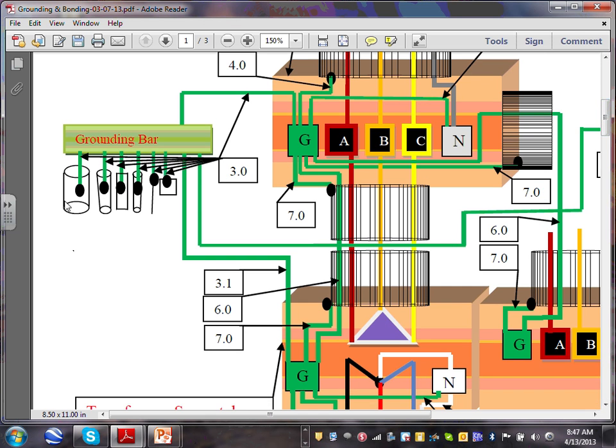Okay, so mind my graphic here, but this is supposed to show that you can use multiple of them, guys. As you know, you can have a ground rod. Let's say that's a ground rod. You can use a ground ring. You can use a ground plate, right? You can use steel if you're building a steel building. You can use a pipe, the water pipe, and I can't remember, that's a tank underground. A buried underground tank qualifies as a grounding electrode system. You only need one of them, but if others exist, you must bond to them.